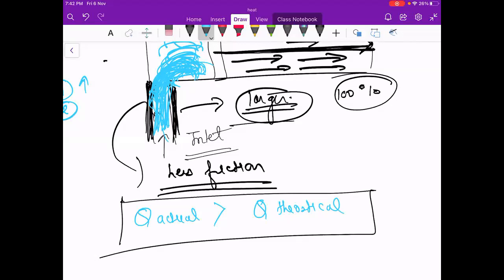Shant, you have said that you have read this before, but you did not understand it at that time. Now you can read this theory. Actually, this is very good theory. What will the interviewer ask? Can Q actual be greater than Q theoretical? We always think that we never exceed the theoretical value, whether it is CRE, mass transfer, or heat transfer. But only in this pump we exceed the theoretical value. So that is a positive thing for us. Hope everyone got this concept.